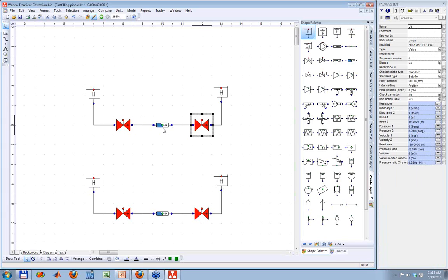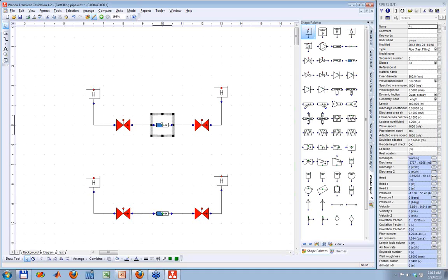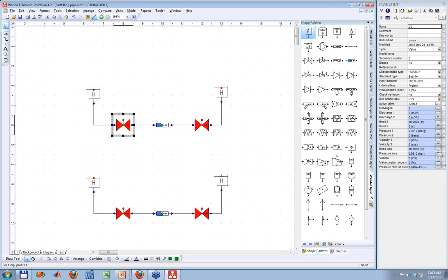During the filling, it can only be filled from one side and not from both sides simultaneously. The air in the pipe is expelled through an air valve, which is located at the end of the pipeline. And of course, that depends on the direction which you're filling in. You can also close this, and then at that moment the air will be compressed and then expanded again, and you get pressure waves going back and forth like that. But at this moment we just completely fill it by opening this valve.